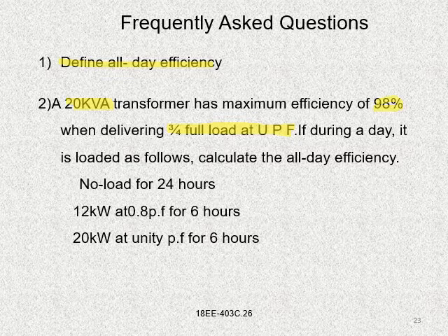If during a day it is loaded as follows, calculate the all day efficiency: no load for 24 hours, 12 kilowatts at 0.8 power factor for 6 hours, and 20 kW at unity power factor for 6 hours.